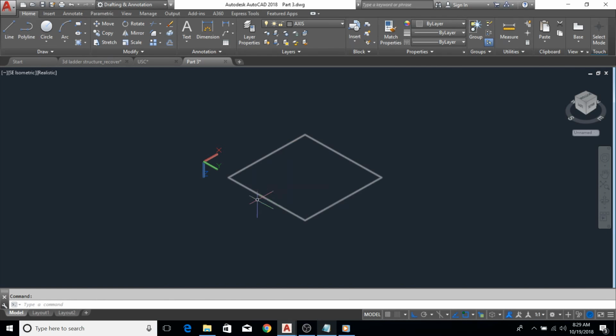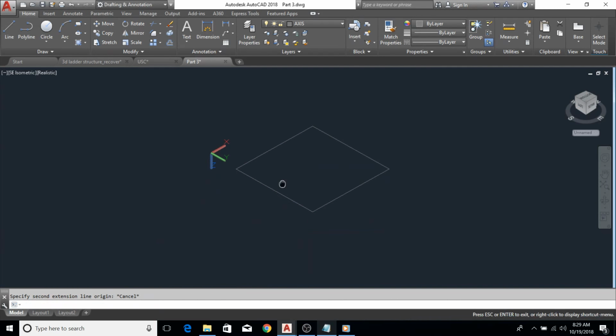To cross-check, you can just pick the dimension. From here to here is 240, from here to here is 240. All right, so I have the center point and the four corners of my structural steel platform. I'm now going to start drawing the section of the column.